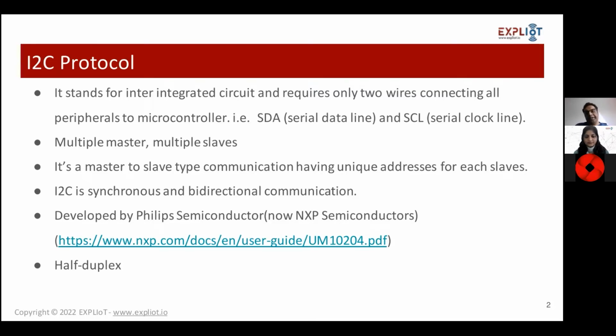Unlike UART communication, where you have a receiver and a transmitter, with the RX and TX pins at both sides, you are transmitting data based on a format where the transmitter first sends a start bit, followed by 5 to 8 bits of data, and if needed it can add a parity bit and then a stop bit. So this is for one frame, or one character. The same thing happens again and again, so these things keep adding overhead for that particular protocol.